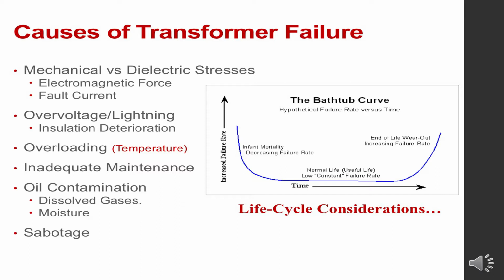And typically a basic insulation level for a transformer, like in an industrial setting, would be 95,000 volts, regardless of the system voltage up to that value. And what they're saying here is how much over voltage has that transformer been designed to handle. So if you're in a part of the country that has a lot of lightning problems, you'll want to, of course, consider using a higher level of basic insulation level on the transformers that you spec out for your system.